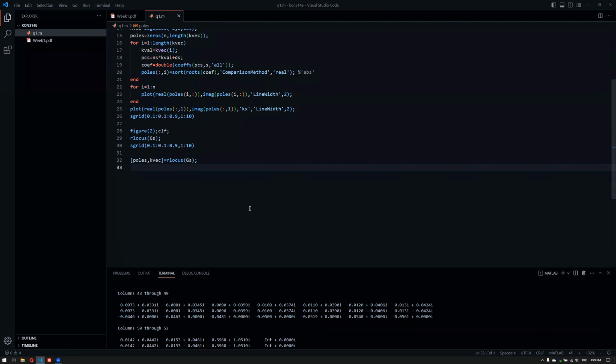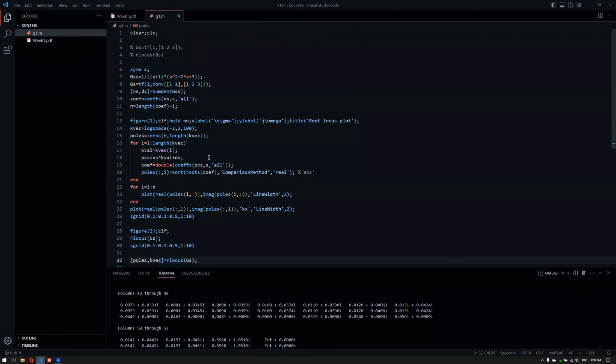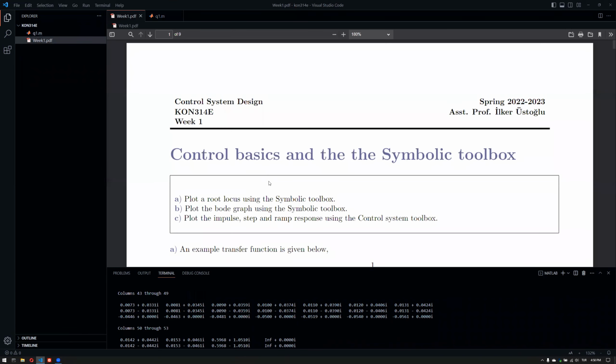And when you're trying to design a controller using the Root-locus, you have this numerical data written down. You don't really have to click and try to locate it exactly on top of a value, because you can search for a value in these vectors or matrices, and you will get your response directly. So I would recommend you to try that out. So this was the first part of our discussion today. Let us just straight away jump to the second part, which is the Bode graph.